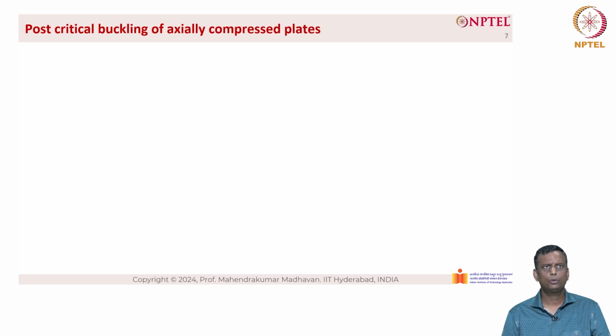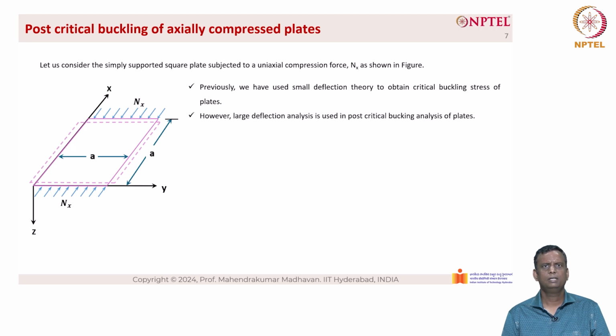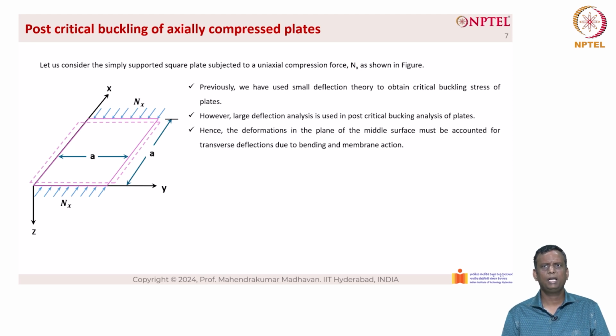Now let us study the post critical buckling of axially compressed plates. So let us consider the simply supported square plate subjected to uniaxial compression force Nx as shown in the figure below. Previously, we have used small deflection theory to obtain the critical buckling stress of plates. However, large deflection analysis is used in post-critical buckling analysis of plates. Hence, the deformations in the plane of the middle surface must be accounted for.